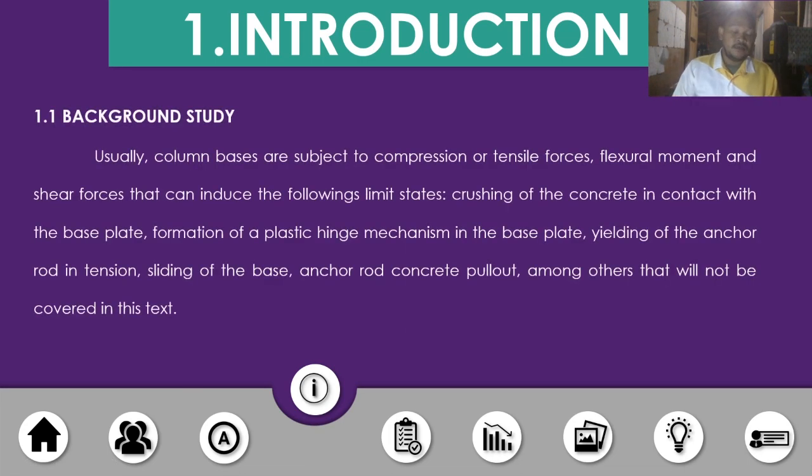So usually column bases are subject to compressive or tensile forces, flexural moment, and shear forces that can induce the following limit states: crushing of the concrete in contact with the base plate, formation of plastic hinge mechanism in the base plate, yielding of the anchor rod in tension, sliding of the base, anchor rod concrete pull out, among others that will not be covered in this text.